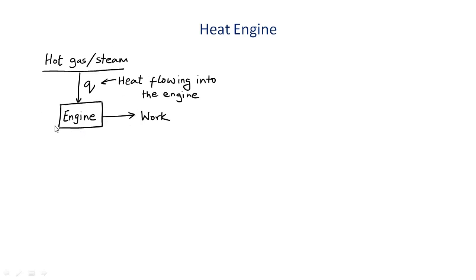The way we have represented this engine, it looks like all the heat is converted to work. This is certainly desirable, but experience shows that this is never the case. As you know, the engine in a car or motorcycle gives off hot exhaust gases. So clearly, there is some heat leaving the engine. The engine can be more accurately represented schematically like this.